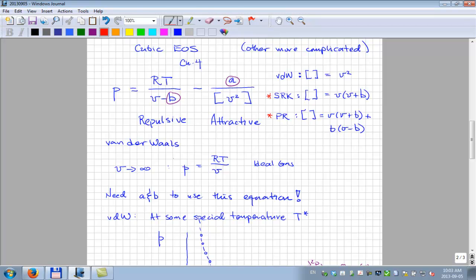In reality, my standing bet is that if you have an SRK equation of state that you say is best, that I have to have the SRK, then I'll make you a bet of $1,000 that I can construct a Peng-Robinson equation of state that gives essentially the same behavior for all the mixtures of interest as yours. It doesn't mean that there's not a reason to have a favorite or a familiar. You work with what's familiar. But in reality, it's like two sets of units. You generally can get the same quality of description of data with either one of them. So, okay, we'll take a break.